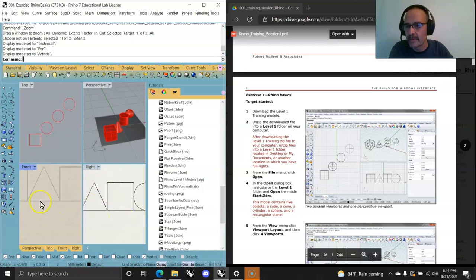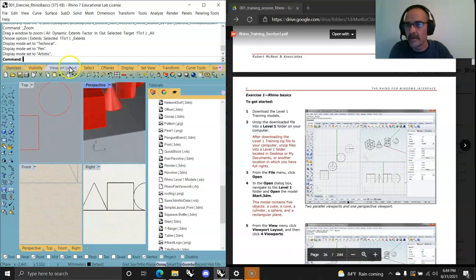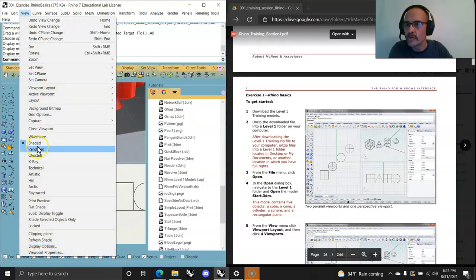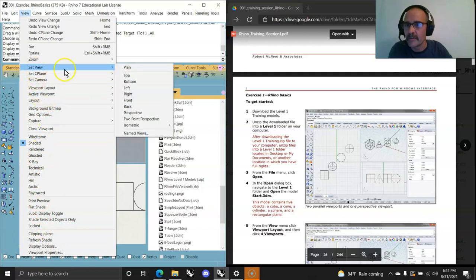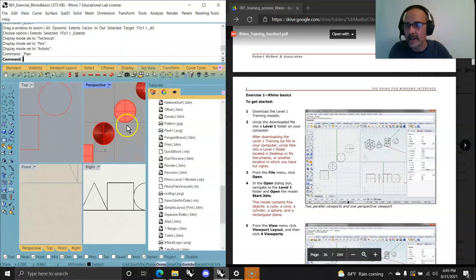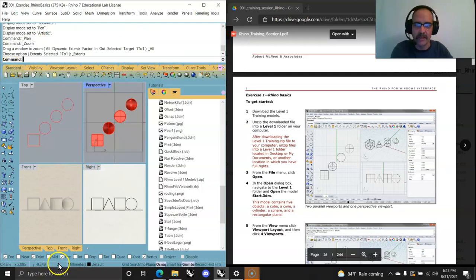And if you make it all messed up and you don't know where your forms are and you get lost in Rhino, there are many ways to recover. I'll just show you basically View Tool. I don't use this one very often. Let me see, Set View and Plan, and it'll reset that plan. But I find I'm stuck on standard views, Zoom Extents All, and everything's back.